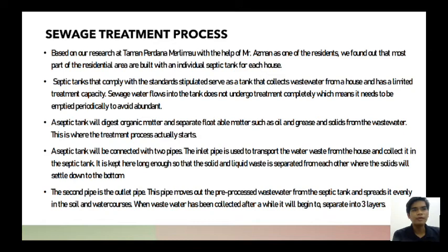The septic tank will digest organic matter and separate floatable matter such as oil and grease and solids from the wastewater. This is where the treatment process actually starts. The septic tank will be connected with two pipes. The inlet pipe is used to transport the wastewater from the house and collect it in the septic tank.